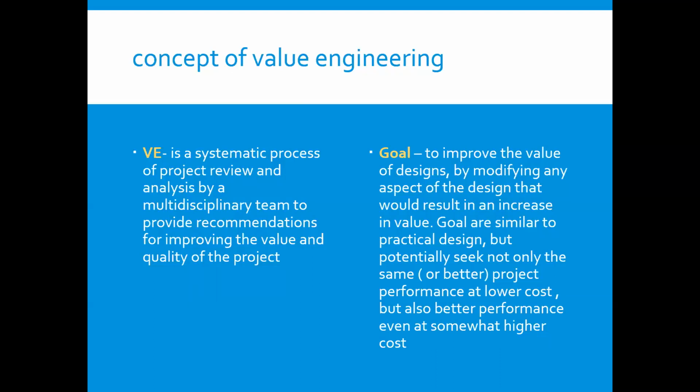Carried to its logical conclusion, performance-based design could have the goal of meeting specific operational and safety targets established by the road agency for each major road project. A performance-based design process involves, at a minimum, estimating the operational and safety effects of each design decision for which it is feasible to make such estimates with available tools, and so consider those estimates explicitly in